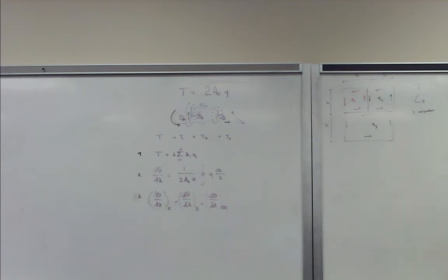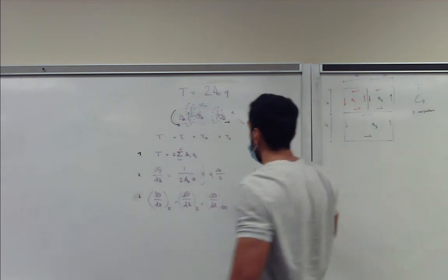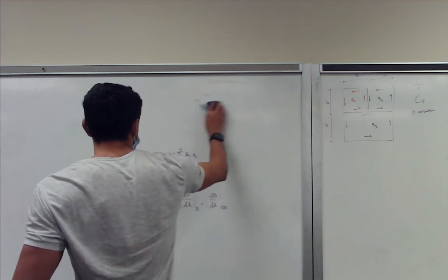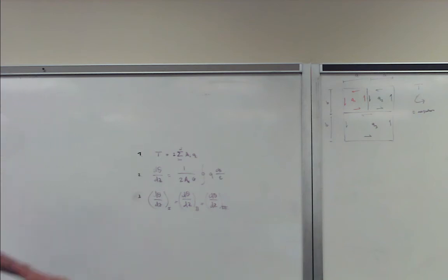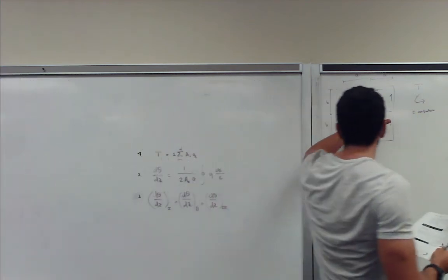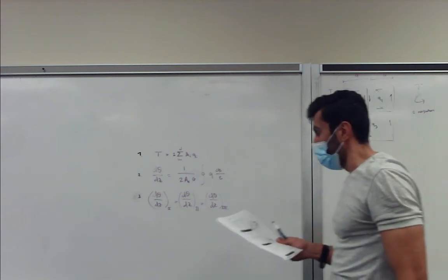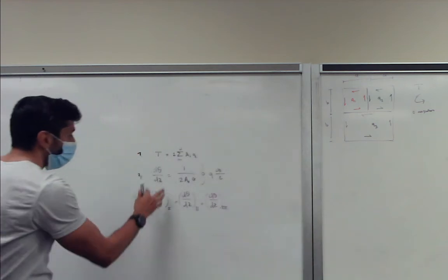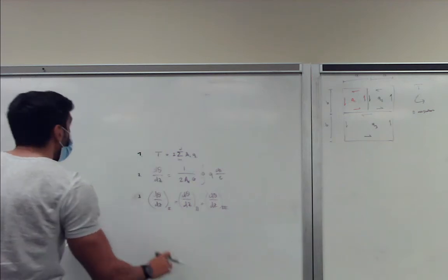And we know by definition that the individual torque components summed up must equal the total torque. And we know that dθ/dz in cell 1 must be equal to cell 2, and dθ/dz of cell 1 must also be equal to cell 3. So now what we can do is use these two equations to see what we have. And we can start with cell 1.